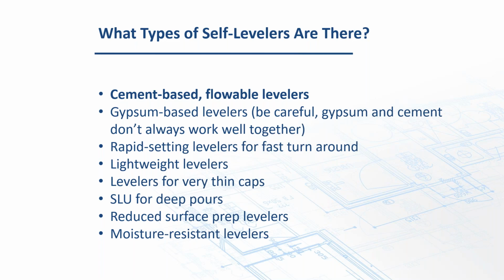And there are moisture resistant levelers. We commonly use these in go early construction. Sometimes we'll get asked to go in and start leveling a project before the walls are even built, meaning the outside weather is kept out by walls, but not the interior. Why? Because then they can put in moisture mitigation type materials and then put a leveler over the top of them, come in there and drop steel frame doors, things like that, and be fairly easy because their substrate's level. It's go early construction, commonly done in hospitals, some schools, etc.